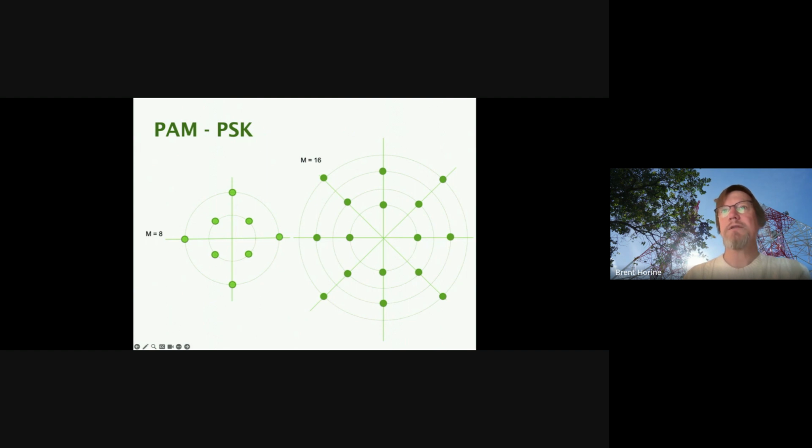So here, this is another way we can implement an M equals 8 type of constellation. Instead of trying to squeeze 8 of these all around in a single circle, let's do 2 circles, right? And you'll see that we're still attempting to keep most of these points pretty far apart, right? So here, these guys are, maybe you could call that a cross or a plus sign.